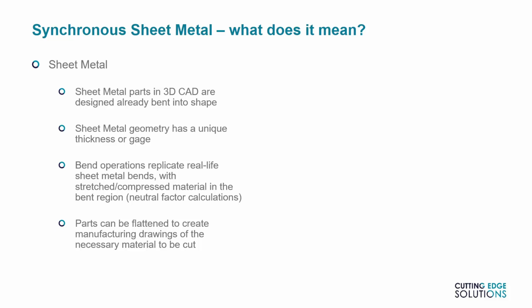In addition to this rule, all bends in this material can be flattened with a mathematical operator that relies on the material properties of the sheet metal in question. This means that, when flattened, the virtual sheet metal material behaves like it would in real life, providing accurate dimensions for the machined blank.